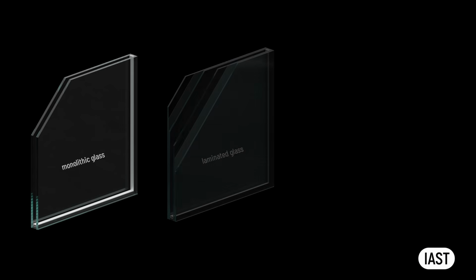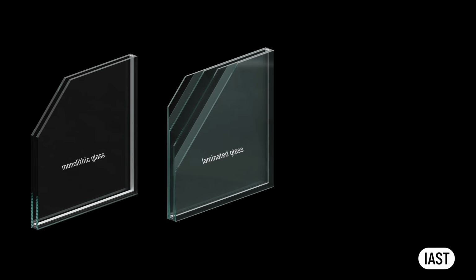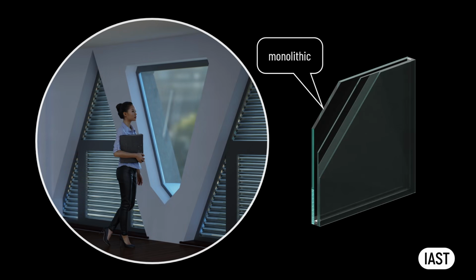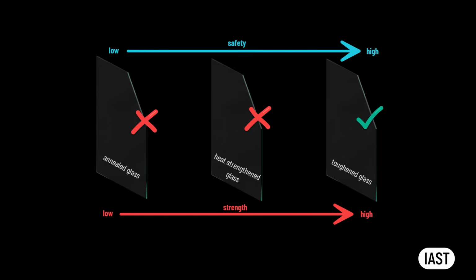It goes without saying that the use of monolithic annealed or heat-strengthened monolithic glass externally, especially above areas accessible to public or service personnel, is not permissible. The internal pane of glass in this case could be monolithic toughened. It is located at the same level as the building occupants, and in case of breakage, it may inflict minor cuts on the building users. However, the risk of serious injuries is considered to be negligible. This glass is accessible to occupants, so it cannot be monolithic annealed or heat-strengthened.